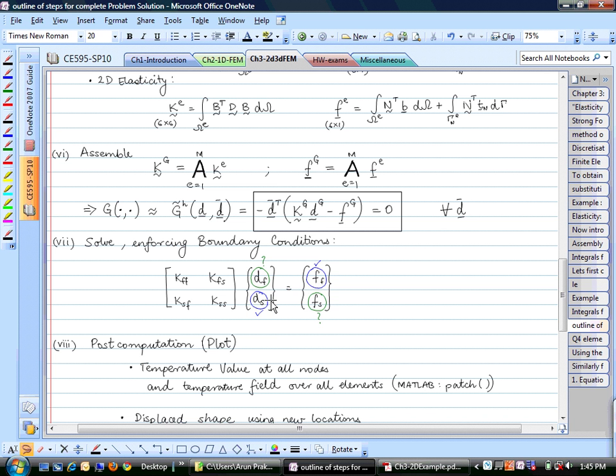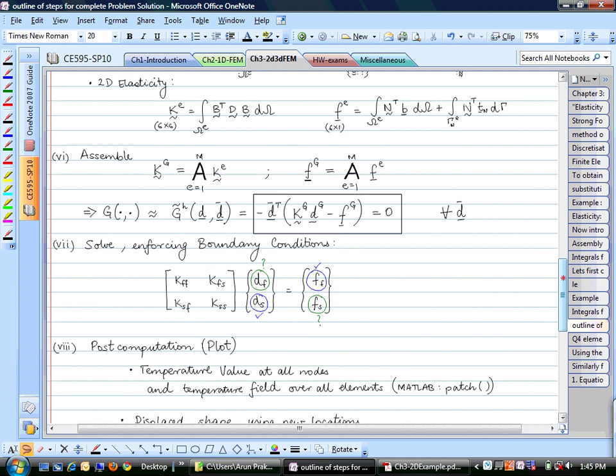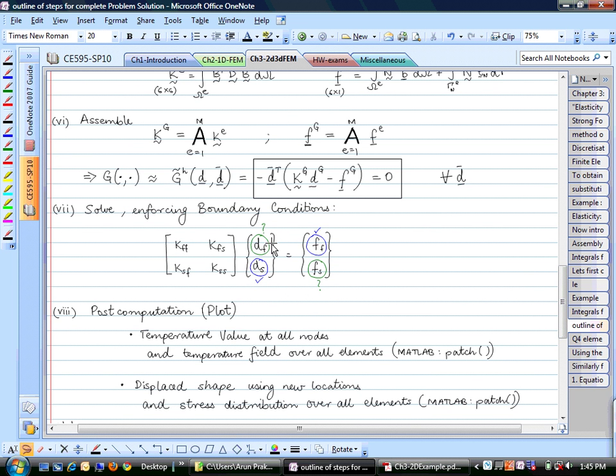This d is just the displacement, right? So to calculate the displacement of each node, let's say node i, it would correspond to degrees of freedom 2i minus 1, comma 2i, right? And then you would pick out those degrees of freedom from this global displacement vector and add it to your original coordinates.